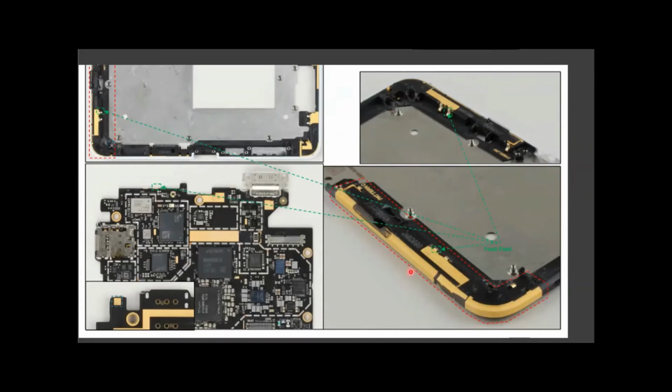So this antenna here is low band, this antenna here is high band, and the gap here and here is slightly different because I'm introducing different types of coupling between this element and this element to control the impedance of the antenna. And there's a feed here and a ground connection here.